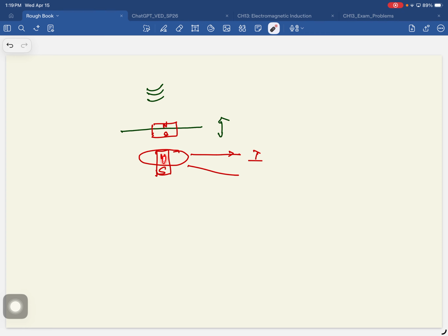As this becomes a magnet, it will make this go back and forth, and it turns the electrical signal into sound. So a speaker and a microphone are opposite things. Now you've learned a very important thing, how to convert motion into an electrical signal. What you need is to attach a magnet to the object that is vibrating and have a sensing coil.